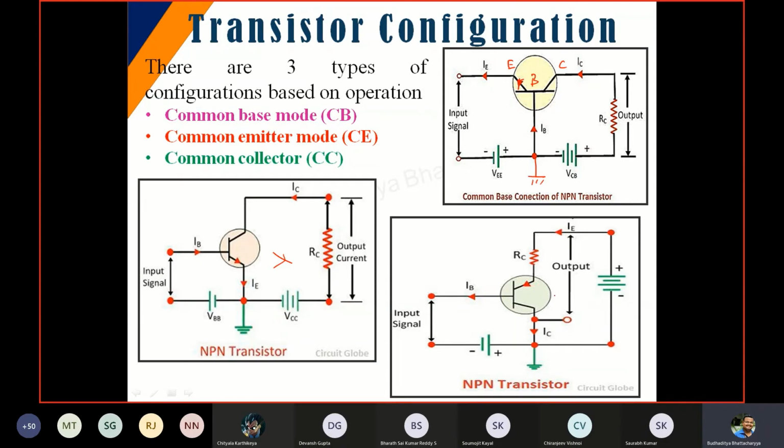Now each of them has their own advantages, and each one of them has their own applications for that matter. One of the most important applications of a transistor happens to be amplification. Remember this, okay? And switching action as well. Amplification will come later in this fourth module, and we will discuss it there. But ideally, these are the two best possible applications of a transistor, in which the CE configuration, the common emitter configuration, is ideally suited for the amplification purpose.